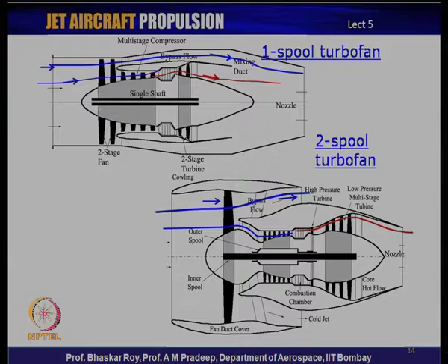In the meantime, a certain amount of flow goes through the compression process, goes through the combustion chamber, through the turbine, and that is the hot gas that produces power. So, the power is produced only by the inner flow. The outer flow does not participate in the power production, it simply consumes the power. The inner flow produces the power through the turbine, and then it goes out and mixes with the cold flow in the mixing zone, and then goes out through the nozzle, a mixed flow, not very hot anymore, but the mass flow of the exhaust flow is now so much more.